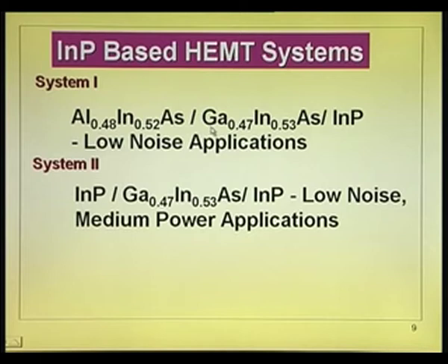So, what they did was remove this particular layer, put indium phosphide, gallium indium arsenide, indium phosphide. 1.46 is the band gap there, 1.35 is the band gap there. So, you get delta EC actually slightly better, but you must be very careful here, do not blindly use the 2/3 formula.